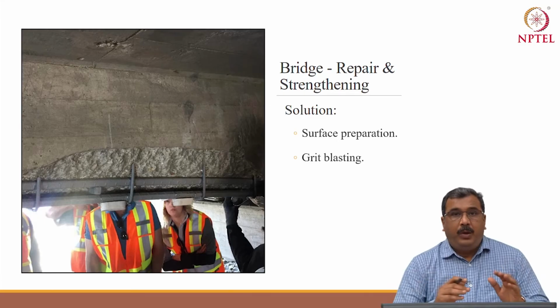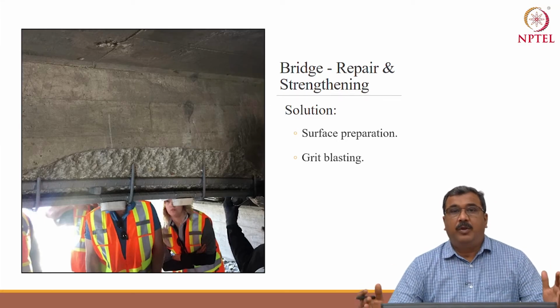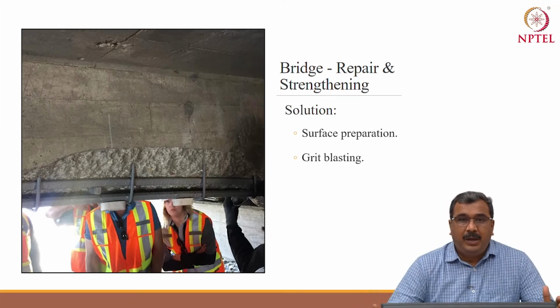So the damaged concrete surface was prepared, steel was cleaned and protected, and electrochemical protection using sacrificial anodes has been installed.